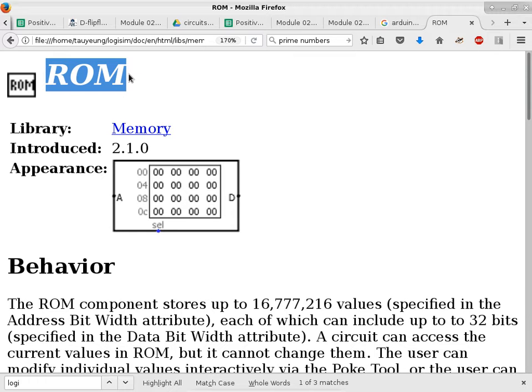And the sector size tends to be pretty small. They range from 128 bytes all the way maybe to kilobytes at the most. So when you have a large flash device, you don't have to erase the entire thing if you want to reprogram just a portion of it. Is that okay?